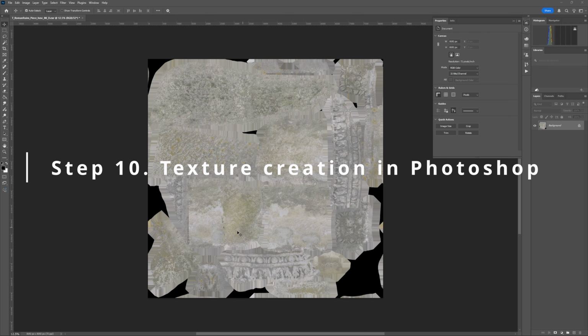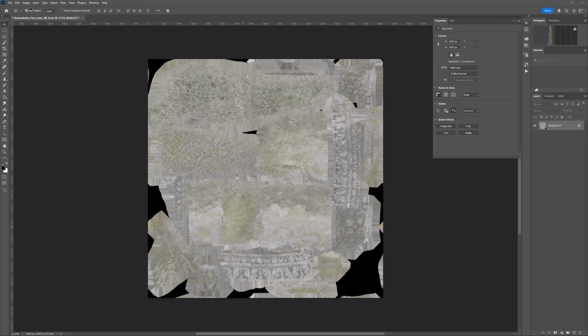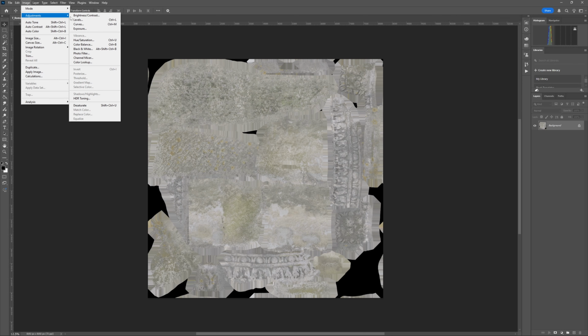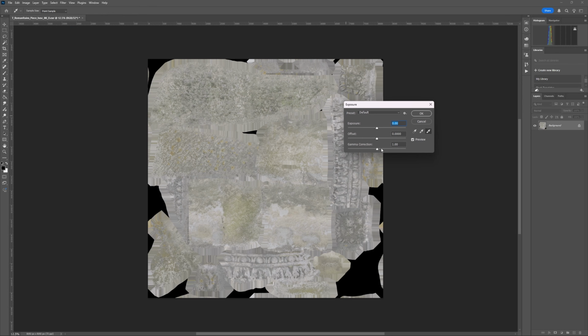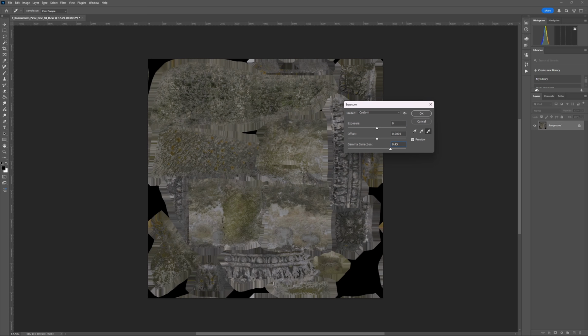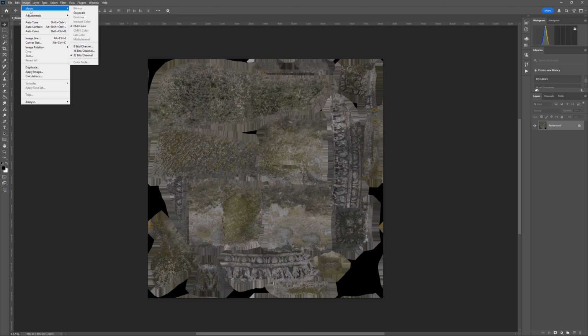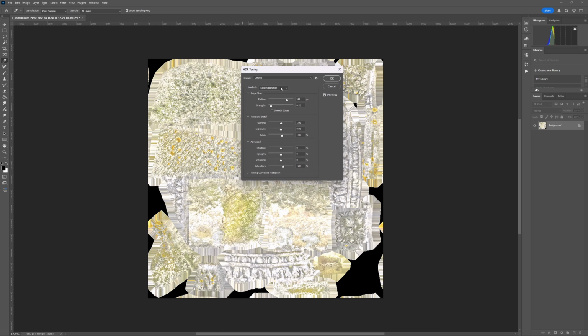You can see it comes in a little bit overbright, so we need to adjust for that. So if we go up to image, and we're gonna fiddle with the exposure. So we're gonna adjust the gamma correction here. So we put it down to 0.4545. And that should be the correct. And then we're gonna convert it to 16-bit and just click it to exposure and gamma.